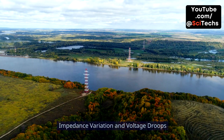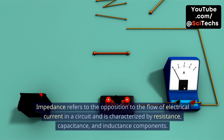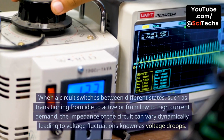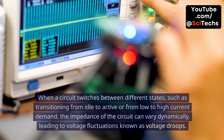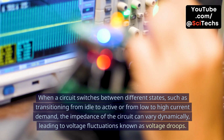Impedance variation and voltage droops. Impedance refers to the opposition to the flow of electrical current in a circuit and is characterized by resistance, capacitance, and inductance components. When a circuit switches between different states, such as transitioning from idle to active or from low to high current demand, the impedance of the circuit can vary dynamically, leading to voltage fluctuations known as voltage droops.